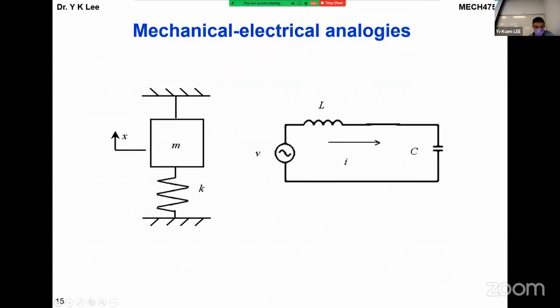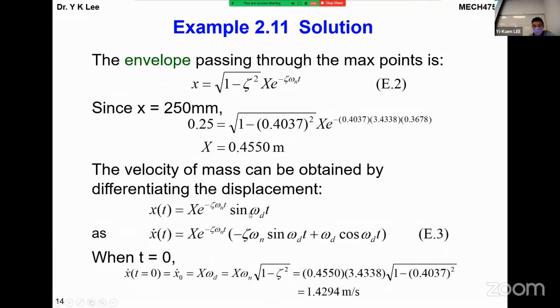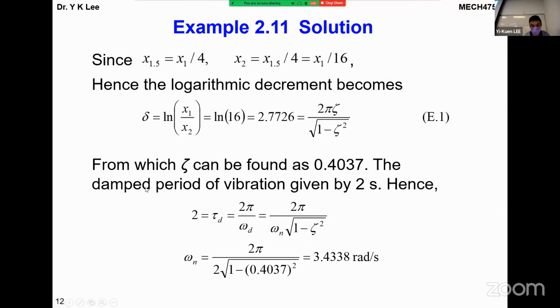And then eventually, what is the most important thing? You need to think about how, once we give you the vibration amplitude as a requirement, to determine the unknown K and C. Add an additional vibration absorber so that you can control the vibration amplitude, vibration velocity or oscillation. It depends on the product, and of course here is only a very simplified way. We do have one chapter showing how we work with vibration standards for different industries. Do you have any questions?